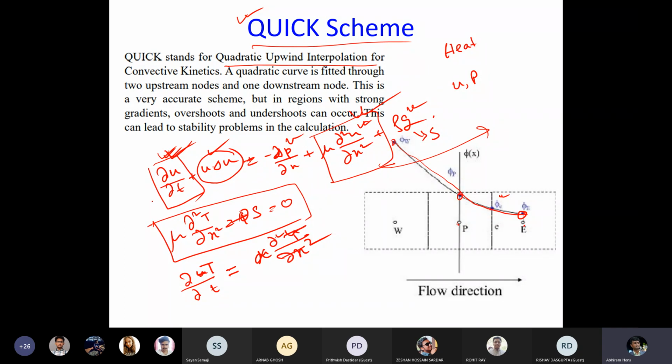Then today we have taken up this part, which shows you how to use the explicit method, the implicit method, and the Crank-Nicolson method, what their advantages and disadvantages are, and what the associated stability criteria are. Now in the last few slides, if you look, we are taking an example of species transport instead of heat transfer, because the same equation can be formulated for heat transfer also.